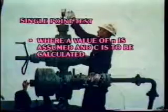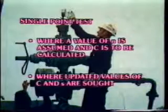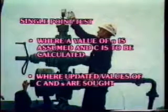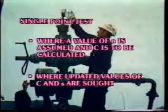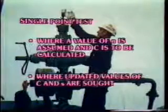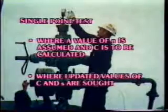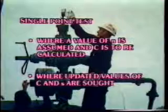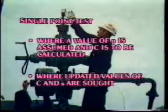The second situation where a single point test is used is in the updating of previous test data. If previous tests have given values for N and the non-Darcy flow coefficient D, then a single point test is sufficient to update values of C and S. This test is often conducted annually as part of a pressure survey. In such cases, the gas is usually produced directly into the pipeline and is not wasted.